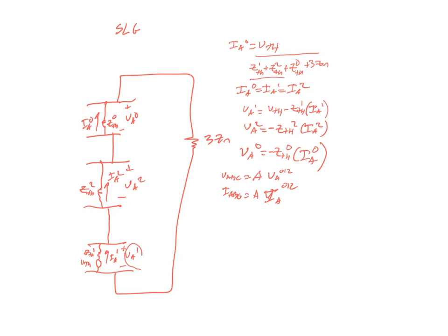Where do you get all these Thevenin equivalent impedances? If you remember, our Z bus is going to have a diagonal. These diagonal elements are all the Z Thevenins seen at each bus. So in row 1, column 1, that's going to be the Thevenin equivalent for bus 1. 2 is bus 2, and on and on and on until we get to bus 11 for this particular example. So we can actually do all the work and automate it that way and figure out what the values are. That's the single line to ground.